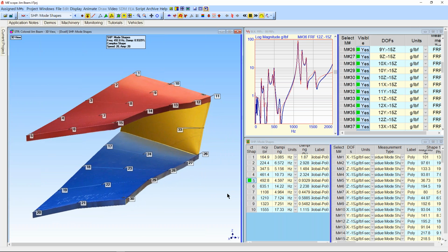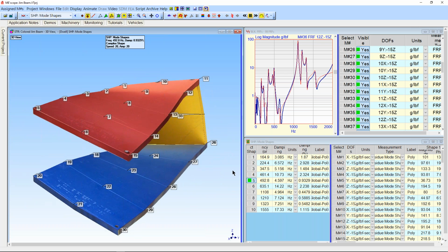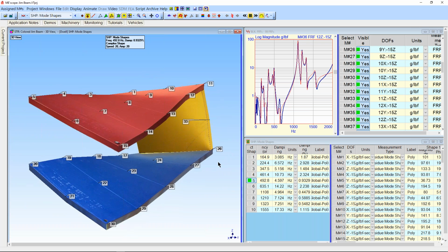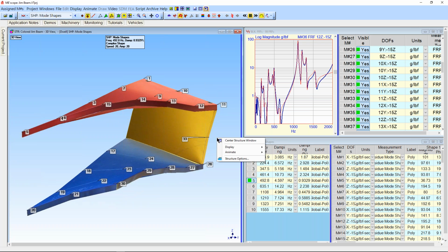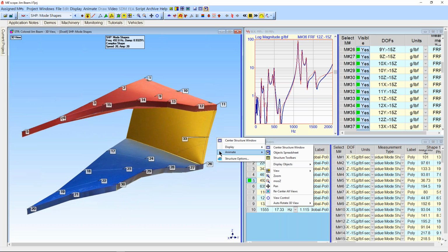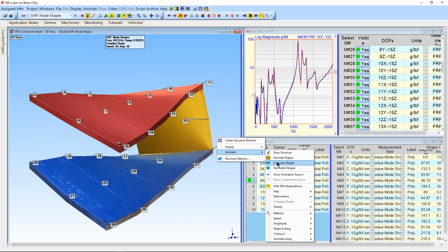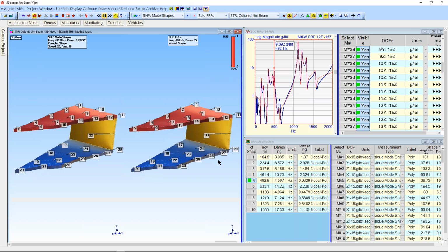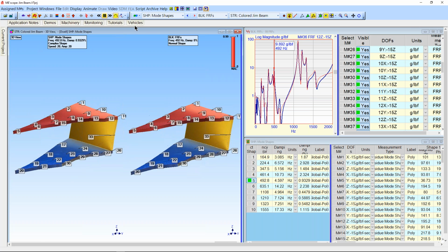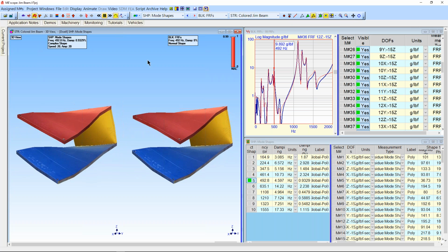Now the other thing I can do is compare the ODSs that we were looking at to begin with to the curve fit results to see how well they match up. This is another way to verify that curve fitting is doing its job. So if I go to compare shapes now, let me turn the point labels off here so they'll animate a little better.